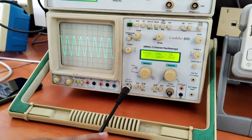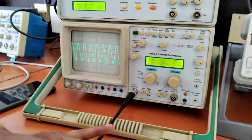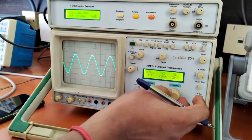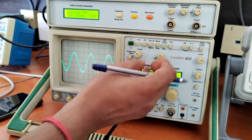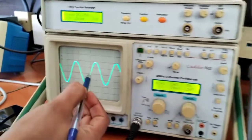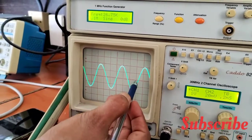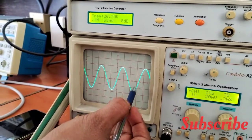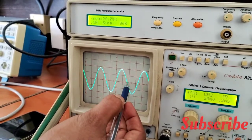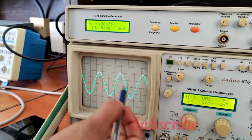Next we will measure the frequency of this signal. For measuring the frequency, we have to measure the number of divisions in one full cycle. Let's say I'm showing here: we can start from here, and the wave starts from here, and one cycle is completed at this point. So we have to count the number of divisions in one full cycle. From here we can count: 1, 2, 3 and 3.4. So approximately 3.4 divisions are coming in one full cycle.